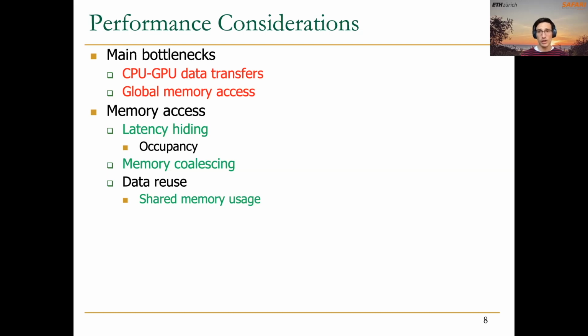We are going to talk a little bit more about that today, but also we will talk about important considerations to take into account when we access the shared memory, because it's a bank memory, and same as in any other bank memory, we can suffer bank conflicts, and these bank conflicts will make the accesses longer and will reduce the sustained bandwidth of access to the shared memory. Then it comes the execution inside the GPU cores themselves.